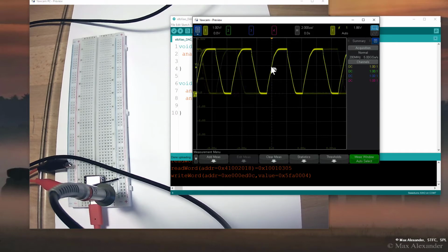And so it's going to go from here, 1 division, to about 2.5 divisions is the execution time. And so that is about 5 microseconds to go on and off. And we see the on time, we see the ramp up for it as well. So it's about 5 microseconds, which is about 200 kilohertz, is the toggle rate going on and off.